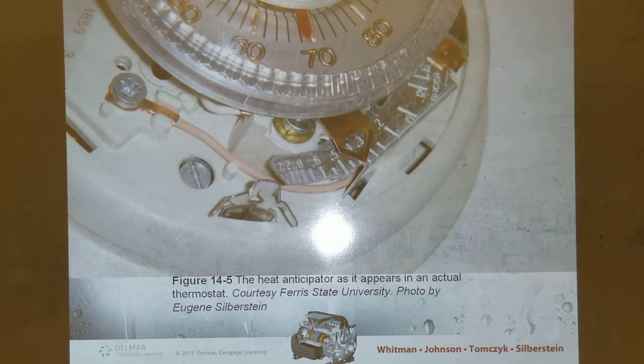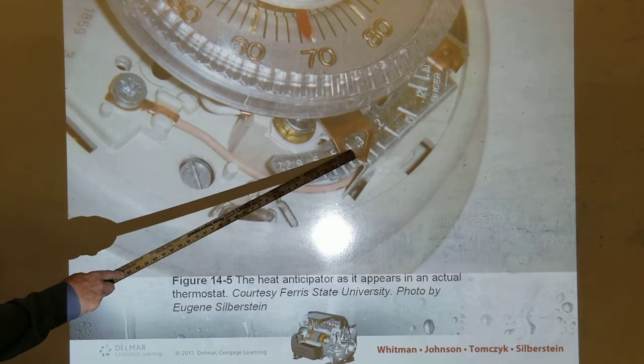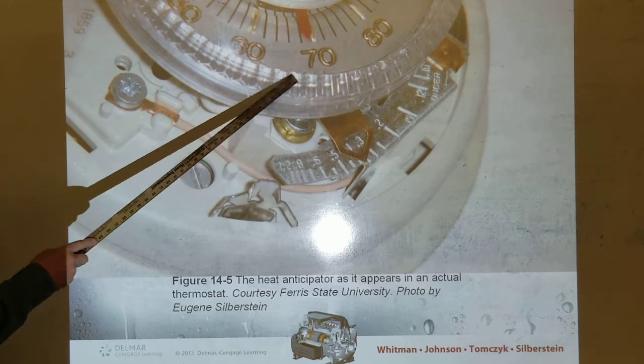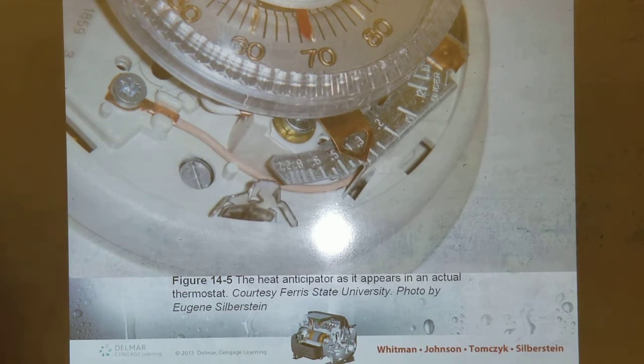It actually turns it off early in order to allow for that heat to flow from the unit through the ductwork and into the house. Because otherwise it would shut off at temperature, and all that heat that's getting put into the room after the temperature is already satisfied will raise the temperature. So it actually reduces the system lag. You understand what I'm saying? No?